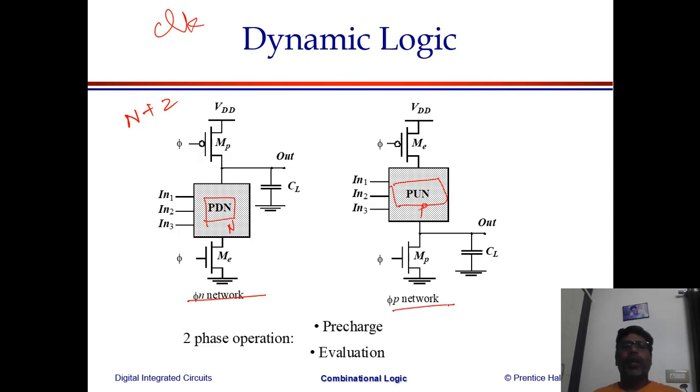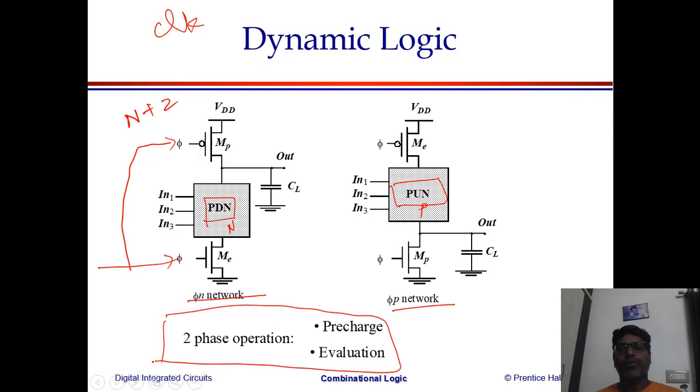One more thing, this works with the clock. As we said, it is going to work with a common clock, but the point to be noted here is it works in two different phases, called the pre-charge and evaluation phase. What do you mean by pre-charge? Pre-charge is nothing but making the clock equal to 0. If you make the clock equal to 0, what is going to happen?